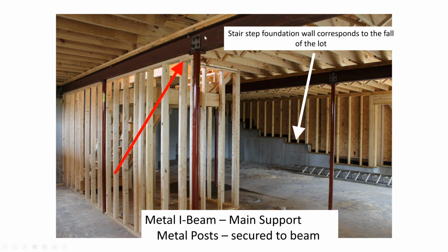These are bolted. This often comes up in a home inspection report where they say that the post is not clipped or screwed into the I-beam, and that'll come up on your inspection report, and that's what that means. They claim that if somebody ran against that post and it wasn't secured to the I-beam, you could move the post.